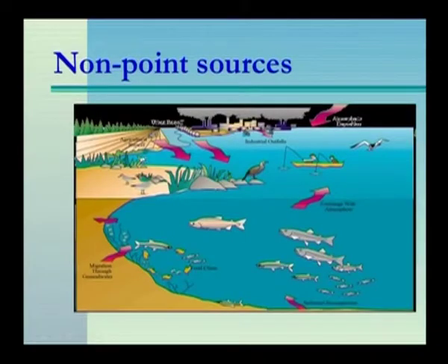Runoff from pesticides and fertilizers could be from hectares of land, and it cannot be said that this is the source or point of origin. Non-point sources, like I just said, could happen anywhere. It could be runoff from the industries, it could be from soil fertilizer, it could be from rivers that are carrying it from upper levels of the mountains and any of this. So, when you test this water now, it could be polluted. But to point and say this water is polluted because of this factor is not going to be possible.